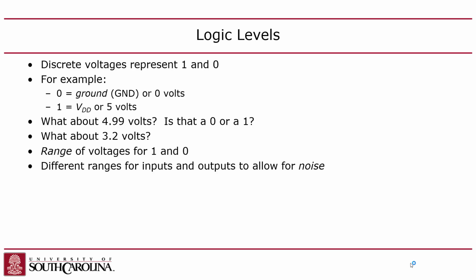And so the signals that are sent and received between gates are analog values. They can either be voltage values if you're using voltage mode logic, or they can be currents if you're using current mode logic. Virtually all digital logic these days is voltage mode logic, but it is possible to create current mode logic.